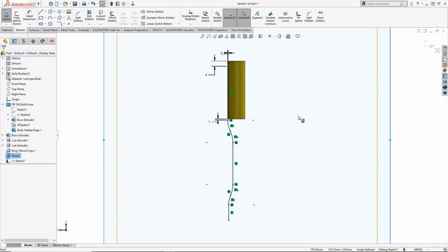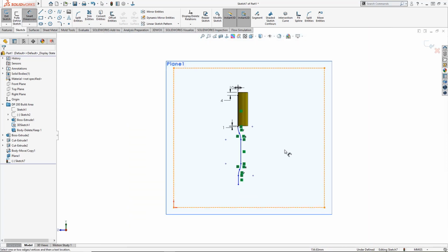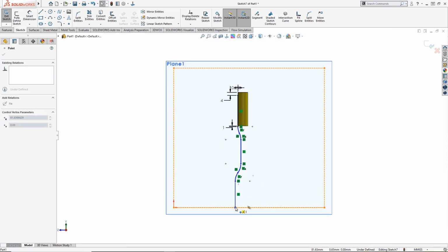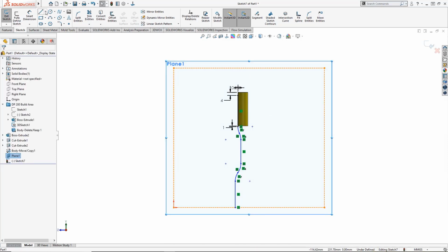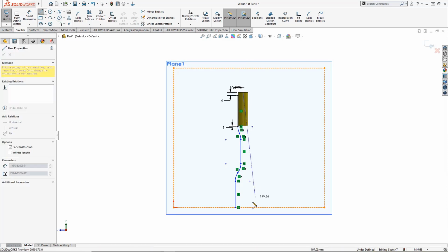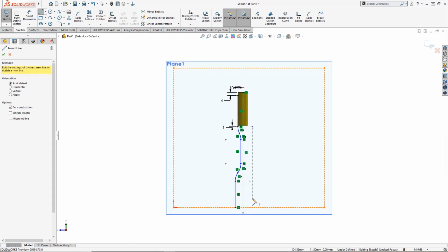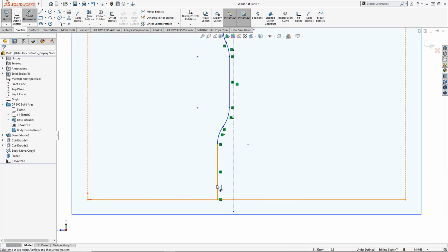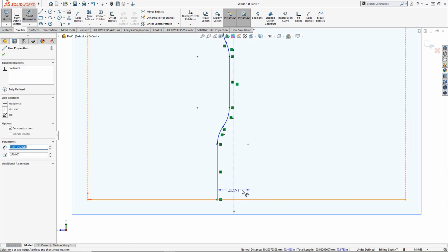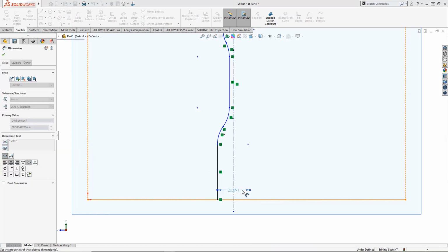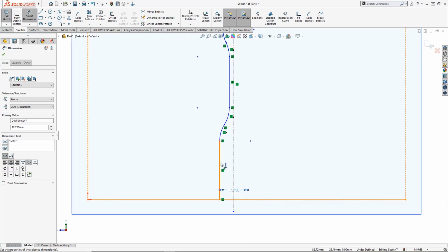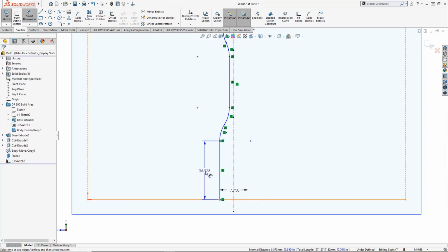Okay, so we're in the middle of my print bed area. So what I want to do here, first of all, is just make sure that this thing's sitting on the floor. I can snap to my bounding box, and that's going to take care of that. The top edge of my orange box is my top constraint, so I can't violate that. Now this is a round part eventually, so if you remember the trick that if you dimension to a center line, it's going to automatically double it if you place your cursor to the opposite side of that center line before you insert the text.